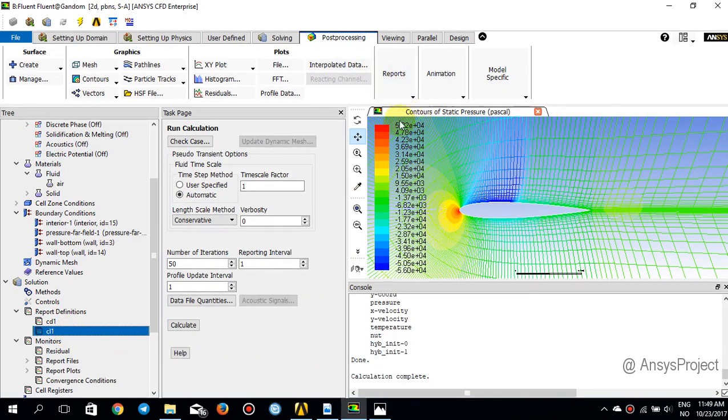So what I would like to do is, in addition to plotting the CD and CL, create a point, just after the shock, downstream of the shock, on top of the wall, and plot the velocity of that point to see how the velocity downstream of the shock is fluctuating, and in order to see if the problem is really converged or not.